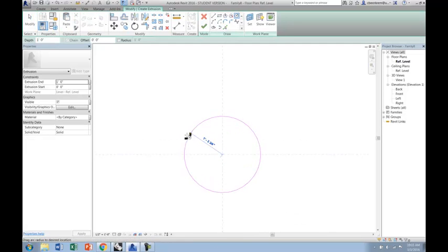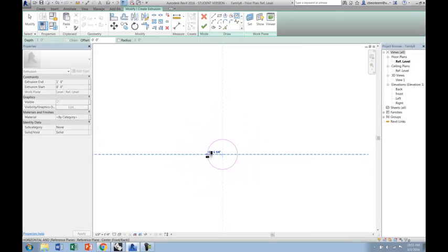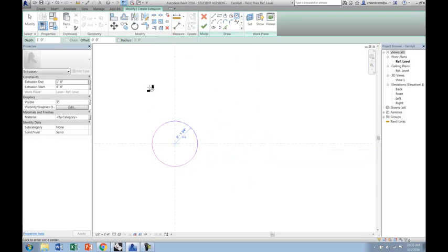You can start off with, say, a 2-inch. Let's go with like 3.5, and then we'll do a line through here, and then offset that line, say 1 inch. We can do a circle in the center, make it half, and now we'll just do some trimming and extending. So there to there, there to there.